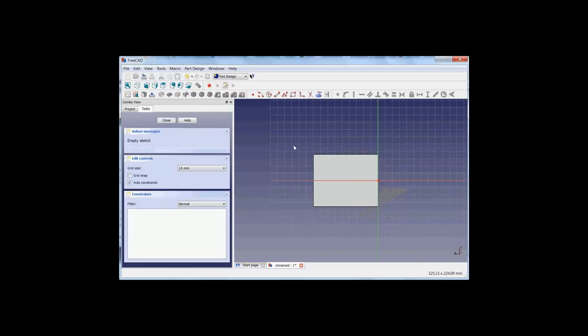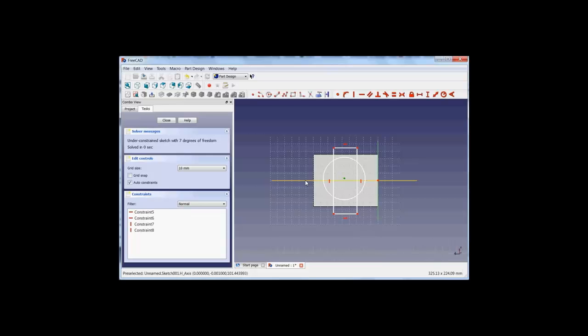Create a sketch. It nicely turns it to where we want it. And this cutout basically consists of a square and a circle, like this. This circle should be on the Z axis, so I select these two and then put them on top of each other. So now the center of the circle is constrained to this axis, and it is 48 high.